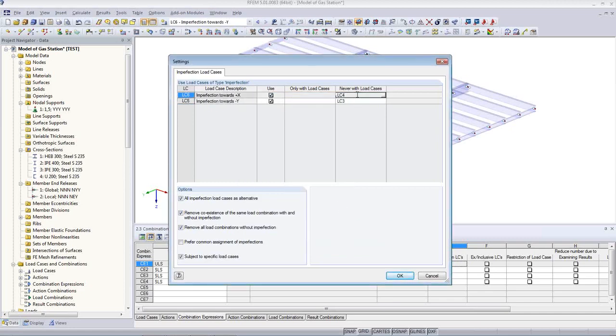If I use common sense, I can figure out which load cases or load case combinations are most likely the one that control, and I don't have to analyze an immense amount of combinations. If you don't want to use it, you can forget about it and just do all combinations, but it will result in longer calculation time and more data to analyze and so on.